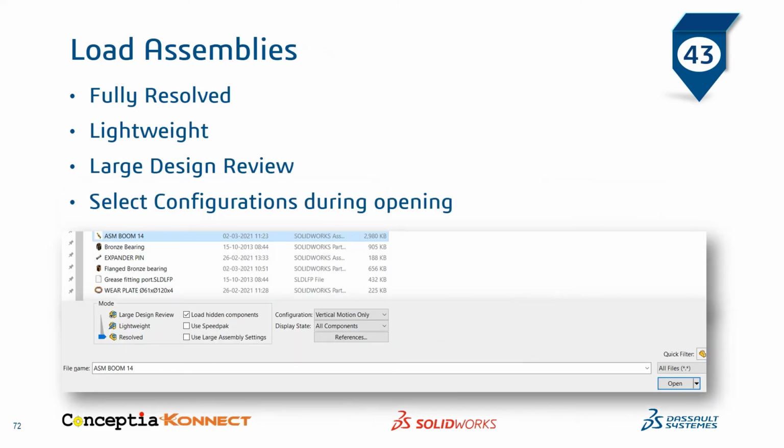Number 43, load assemblies. When you open an assembly, change your assembly mode at the time of opening itself, whether it is fully resolved, lightweight, large design review, and also select the configuration of the assembly, which has to open for you. Save some time for it.